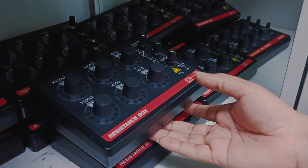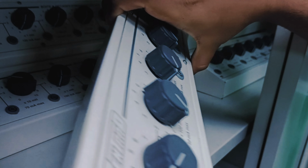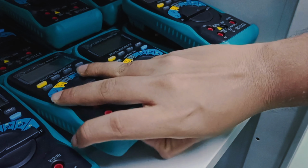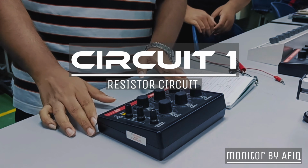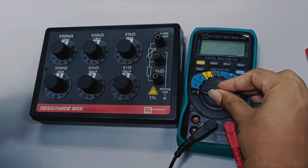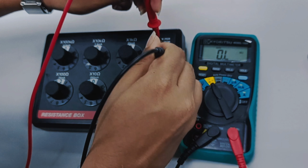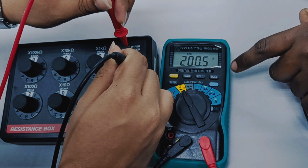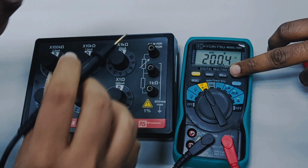On the third day, we go to the lab to construct these 3 circuits. We take all the necessary materials and tools for this project. In this circuit, we adjust the resistor to 200 ohm. Now we turn the knob of the multimeter to the ohm sign. Connect the probes of the multimeter to the legs of the resistor. One probe will be on one side while the other is connected to the other side.